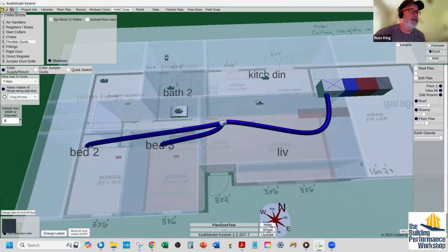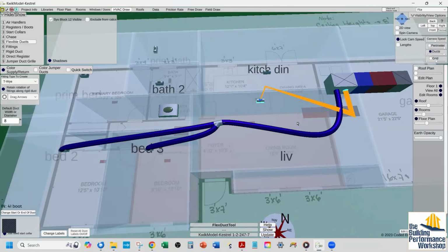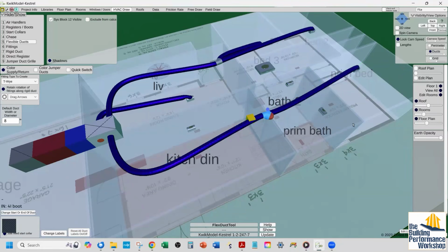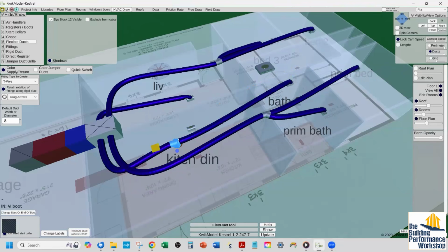Exactly. So my duct design philosophy is, to me, air likes to be symmetrical. If air's coming down a box, it likes to have an equal choice of whether to go left or right. In terms of predictability, if you could split your air perfectly equally, you would be able to predict that, as opposed to saying I want a 60-40 split.